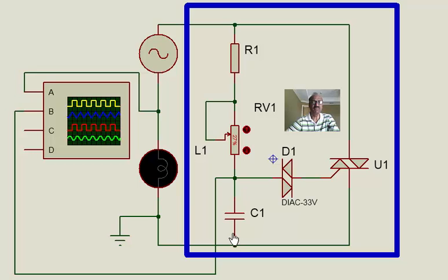And mind you, we are talking about this time in milliseconds, based on the frequency of the supply. Supposing my frequency is 50 Hz, or in places like the US it is 60 Hz. Based on that 50 Hz or 60 Hz, we are talking about that time only. One cycle for 50 Hz will be 1 by 50, that is, one cycle is 20 milliseconds, whereas one half cycle is 10 milliseconds. So we are talking about a 10 millisecond duration as far as the delay of this triggering is concerned. All these will be clear once we go over to the simulation and see the function.